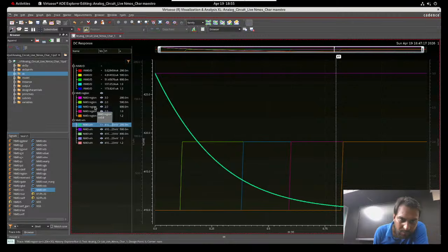So you can understand in such a way what your VTH is and what the effect will be. That is why at 500 millivolt it is showing the saturation region. If you are using a small length, it will have a higher VTH. So I think it is enough for today, we will continue this part.